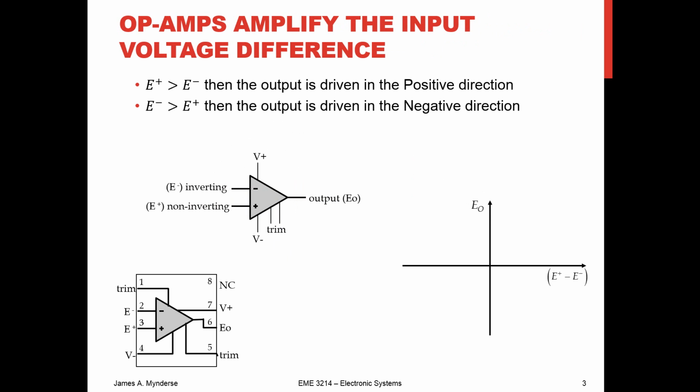Mostly they work like this. We've got the inverting and the non-inverting terminals, the minus and the plus there. We've got two power supply terminals, V plus and V minus, because we've got to provide an external supply. This thing is an active element. And we've got an output. And so you've got your standard 8-pin PDIP package like that. You've seen this one in lab.